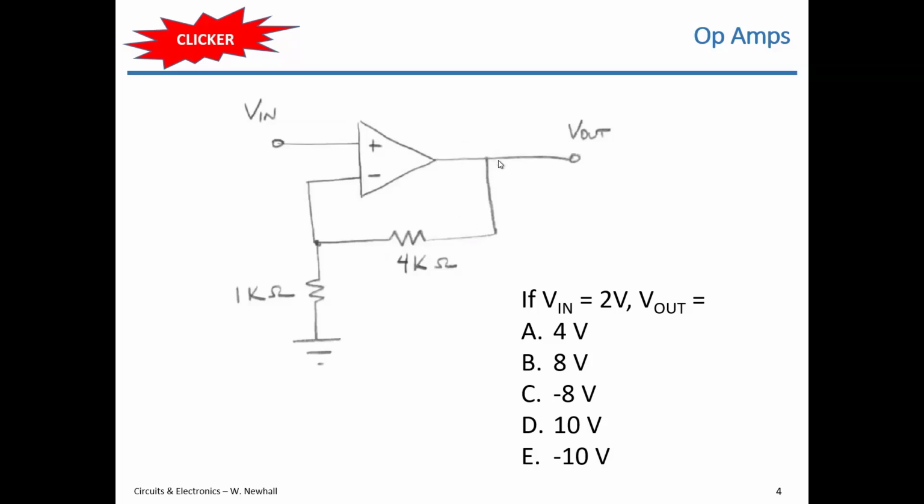That lets the output voltage of the op amp influence the input differential voltage, and specifically the node voltage of the inverting input. If you see negative feedback, you use the negative feedback approach to analyze the circuit. You assume that the input differential voltage is 0 because of negative feedback, and you assume the input currents into the op amp are 0 because it has generally high impedance inputs.